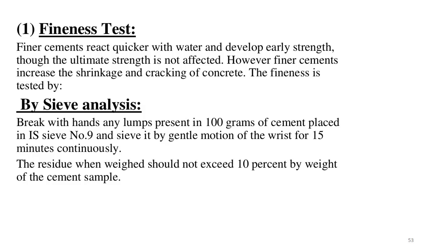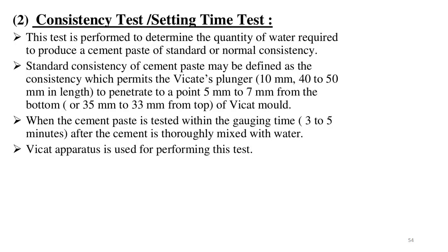On the other hand, the fineness by the sieve method is obsolete in ASTM, but you can use a sieve size around 200, which is 75 micron size. You can use the wet method of fineness by allowing water, with the help of water, the cement particles to pass through sieve number 200, and you just take the weight retained on sieve number 200 after this test.